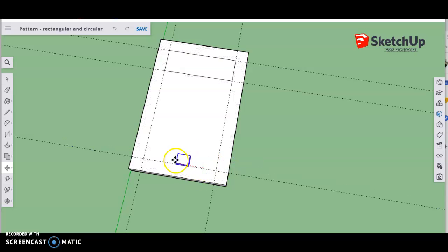Click here, press Option, press the right arrow to stay on the red axis, and I'm going to end it right at this corner here. And now, instead of pressing 5x, I actually want 5 keys total, so I only want 4 copies. So I'm going to do 4 slash. You see in that lower corner here? It's 4 slash. Then press return, and that will fill in the space in between. Okay, so that's the sideways ones.